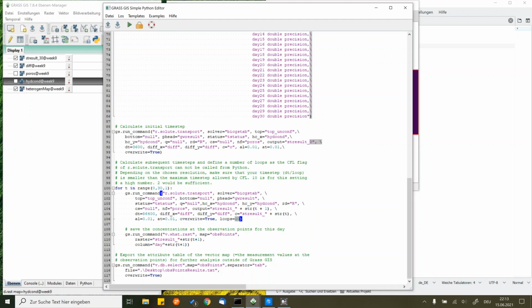If you do not specify it, it will do the full time step in one calculation, which might lead to inaccuracy. But I strongly encourage you to try it out, to play around with those parameters to see what the effect is. In fact, I will do another video demonstrating just the effects of, for example, modifying the time step, but also modifying other things of this simulation.